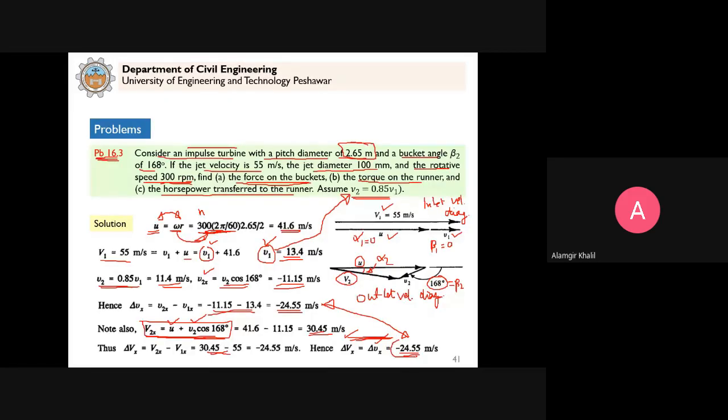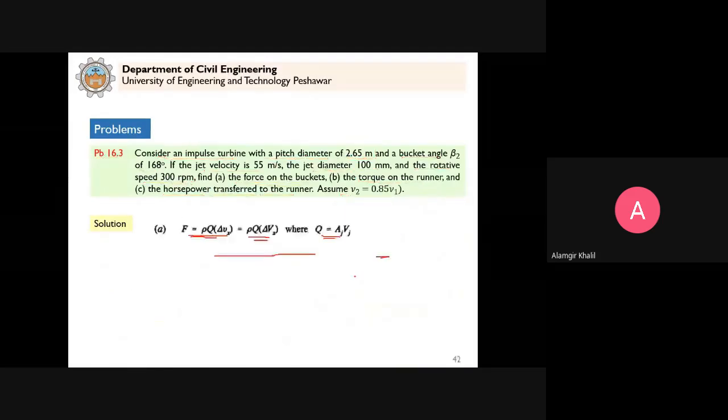Where does this negative answer go? Because this is the bucket, an ellipsoidal bucket with a splitter in the middle. This is the force of the bucket on the water, so it is in the opposite direction; this is negative. This negative makes the negative sign here positive, so we get a plus sign. Clear? And then this is the correct direction.